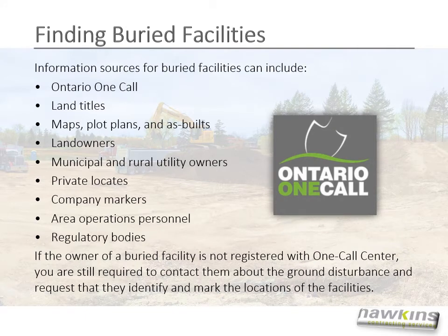We've discussed Ontario One Call as your primary information source for buried facilities, but there are many others that may need to be utilized, such as land titles, maps, plot plans, and as-builts, landowners, municipal and rural utility owners, private locates, company markers, area operations personnel, and regulatory bodies. If the owner of a buried facility is not registered with One Call Center, you are still required to contact them about the ground disturbance and request that they identify and mark the locations of the facilities.